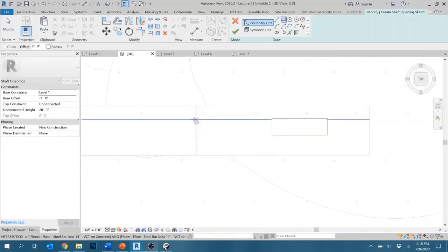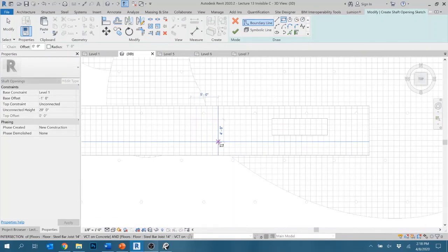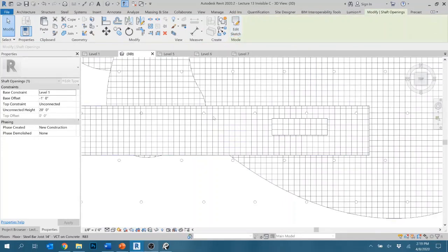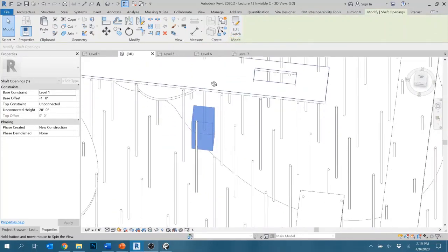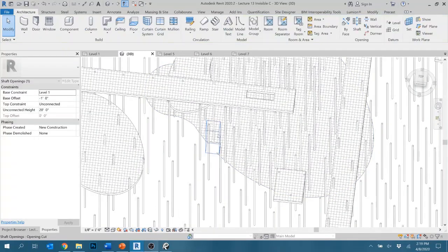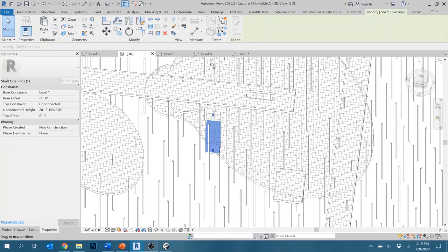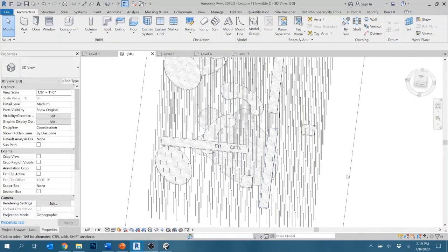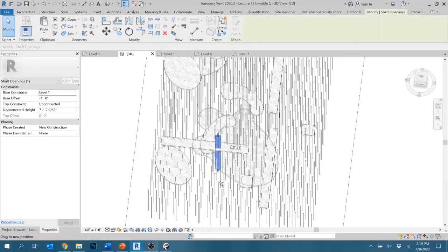What this does is if you have elevators or stairs through multiple floors, this creates an invisible boundary that you can click on in 3D, but that goes away if you are in floor plan or in 3D and not selecting it. See how that goes through both this plane as well as this one.